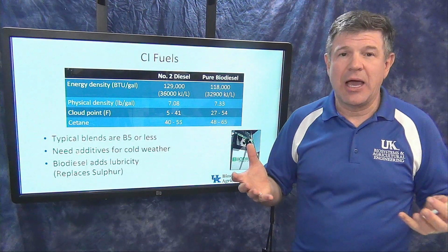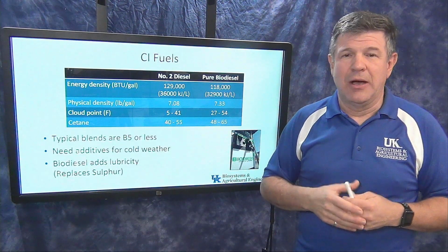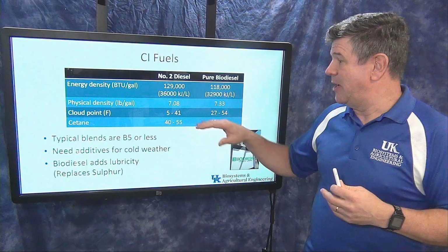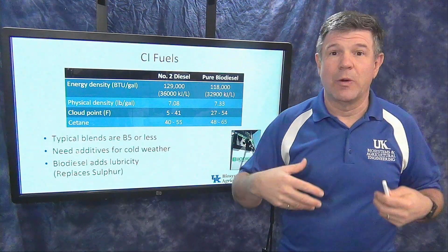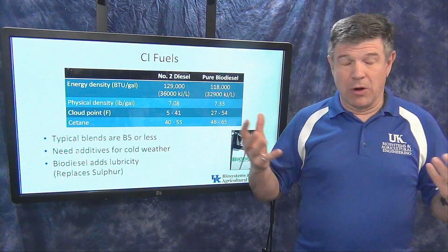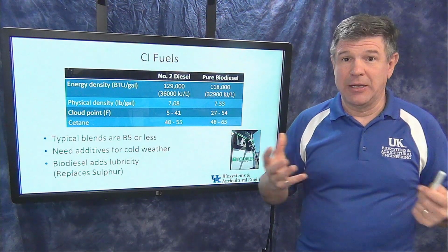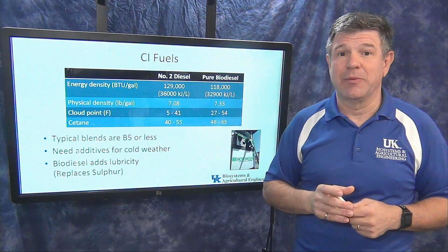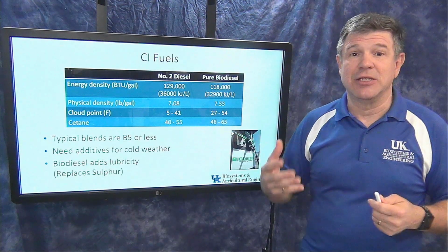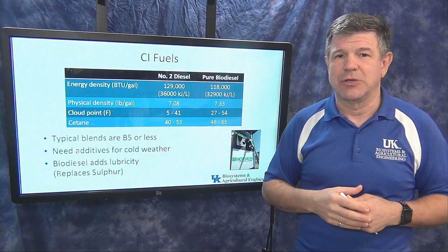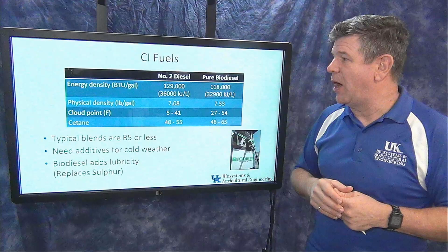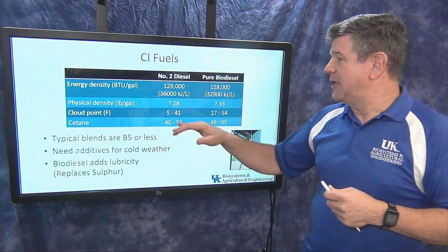And depending on the climate where you're using this vehicle, in the southern United States, it's not that big of a deal, but in the northern U.S. and Canada, for instance, where we're going to see colder temperatures, it's very common, and I need to be able to use that fuel at very cold temperatures. I need to make sure that it stays flowing even at those very cold temperatures. So those are things that I have to watch and be careful about. So that's the cloud point.